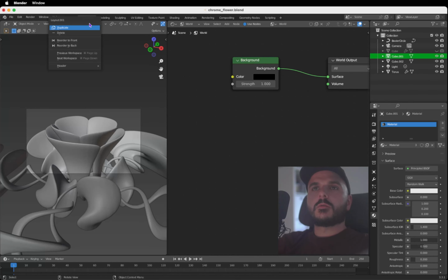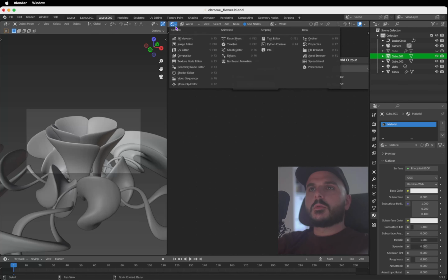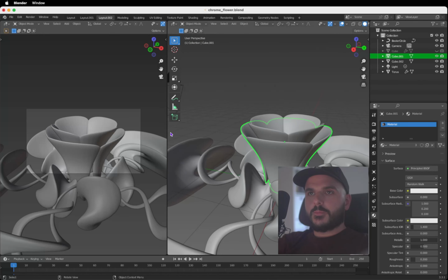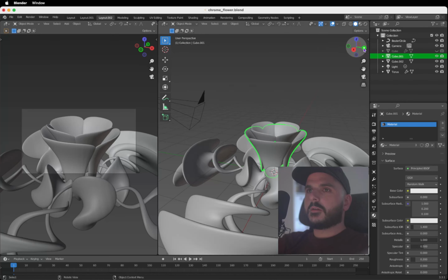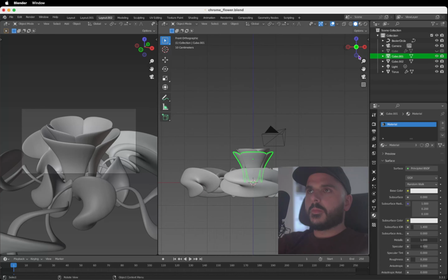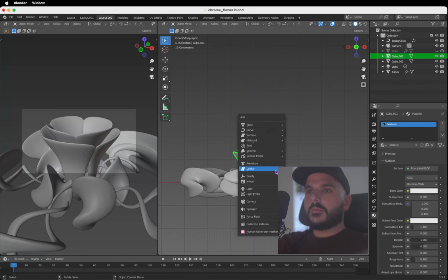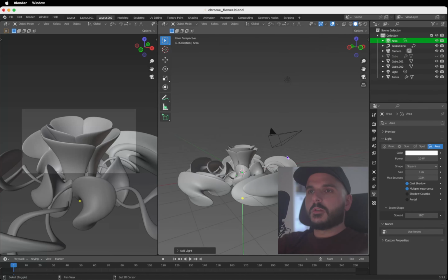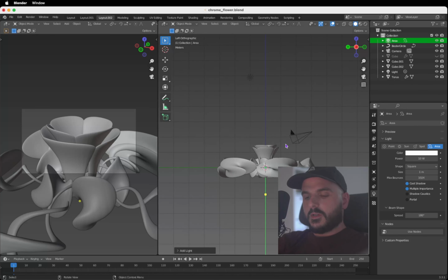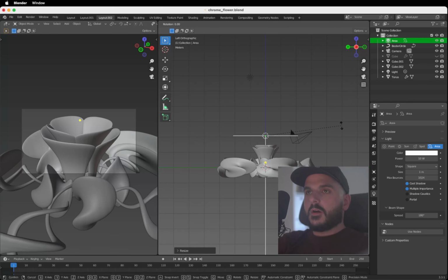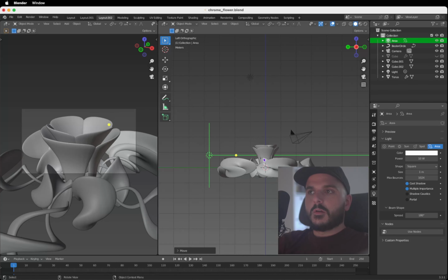Okay, I'm going to duplicate this workspace again, our second one. So right click, duplicate. We change this to 3D viewport. And let's add another light source. So hit Shift A. Choose the area light. You can go to the side view, press G and Z to move it up, S to scale it. Hit R and 90 to rotate, or 180. And give it a power of 1000.